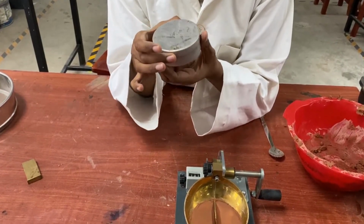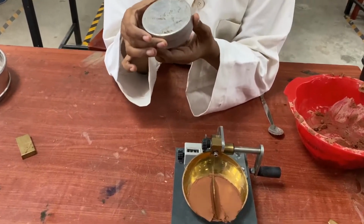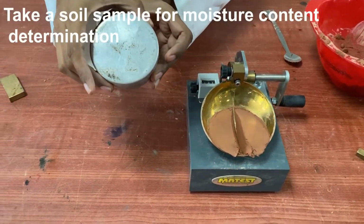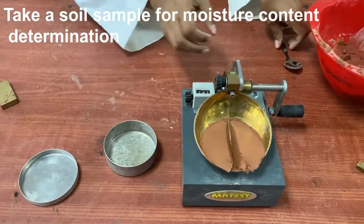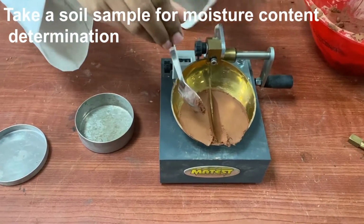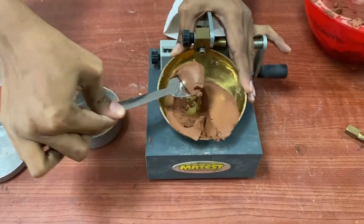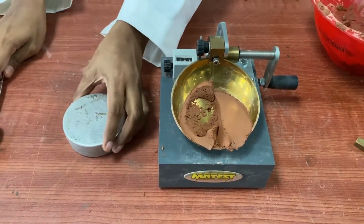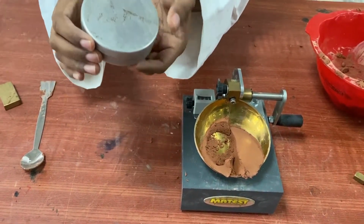This will give you the weight of the empty can and the weight of the dry soil. We have already recorded the weight of the empty can, so quickly we will take some soil sample and measure the weight of the empty can plus the weight of the wet soil.